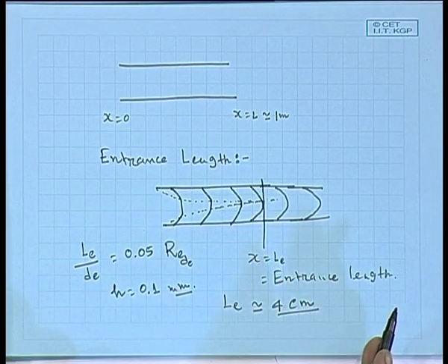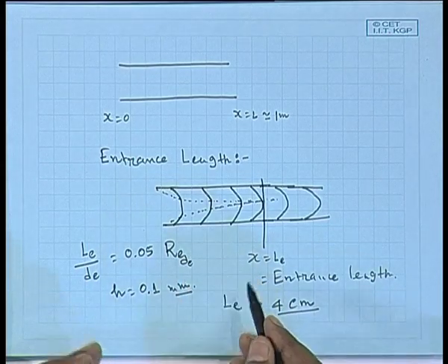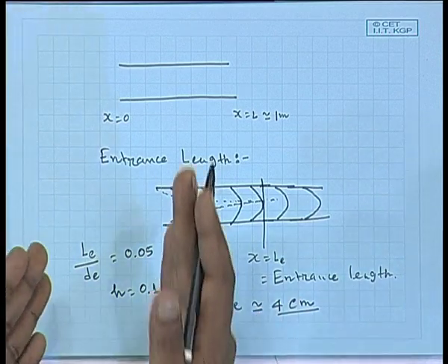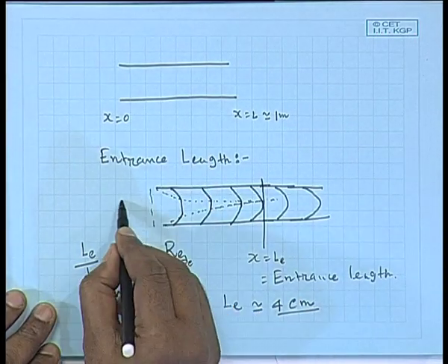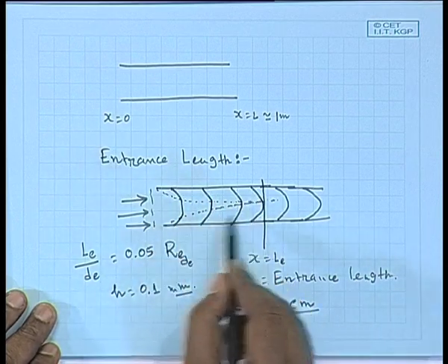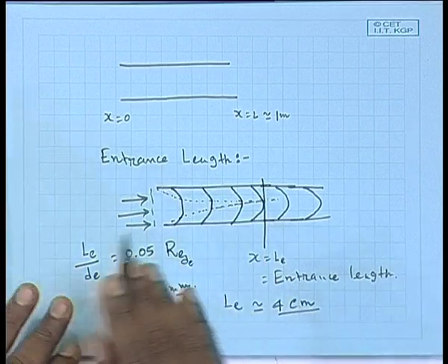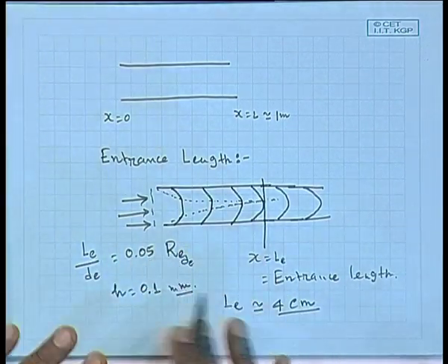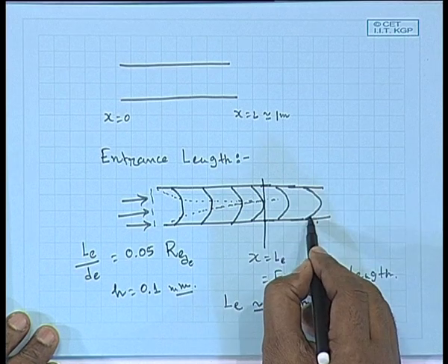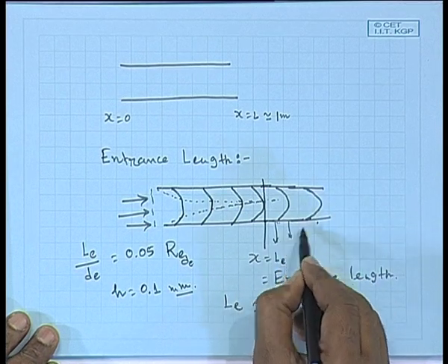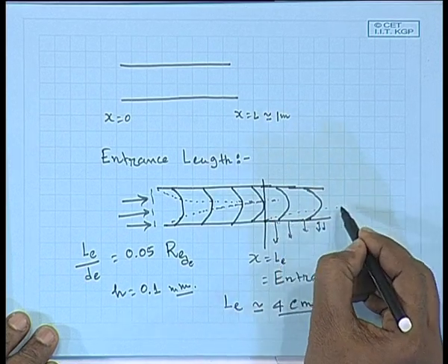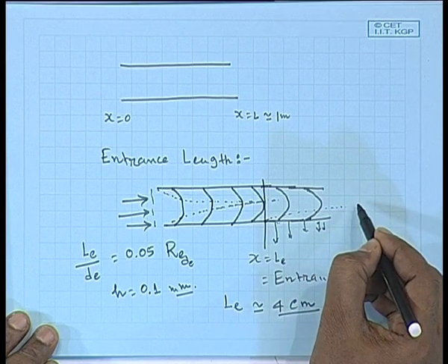Okay. So, there is no effect of suction, the membrane is covered, you are not taking out any water. So, the concentration distribution, the uniform distribution that is entering, will be the same as C naught throughout while it is travelling over the covered portion. After the covered portion, the velocity field is fully developed, and you are taking out water from here, and there will be deposition of the concentrated solute particles over the membrane surface.